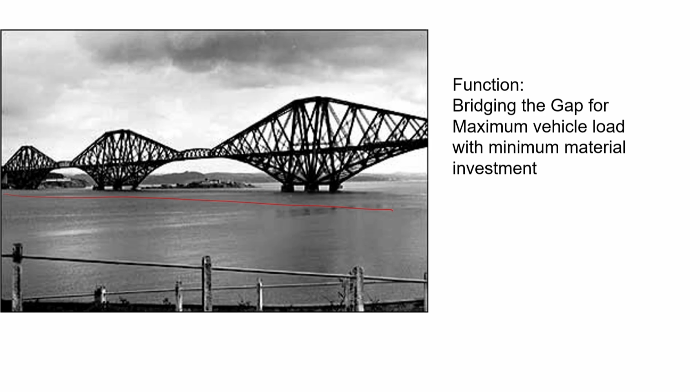So, this design, once upon a time it was made possibly by using cast iron, was an economic design, but then structural steel has been developed, and with that the manufacturing process also has become available, so that you can give much more. We have seen in our last lecture about the shape factor that structural steel has a much higher shape factor. So, today this type of design is not required, because you take advantage of the shape factor and go for other types of bridges like, say, suspension bridges or things like that.